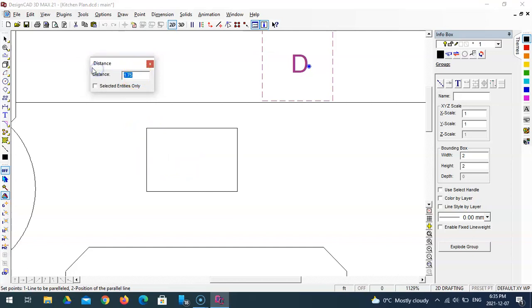So if I type in 2 foot 7 inches, move my mouse away, it will convert it to a decimal. Then I could click in there again and go /2, which is divide by 2. And it gives me 1.2917. So now I should be able to parallel this inwards, 1.2917, and this will be equal to this side.